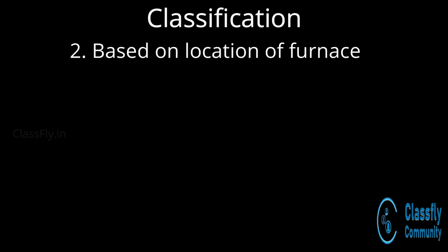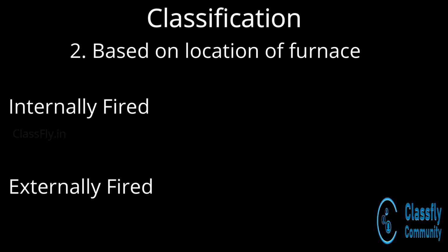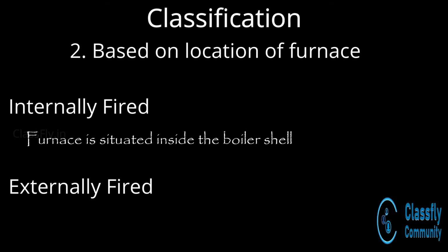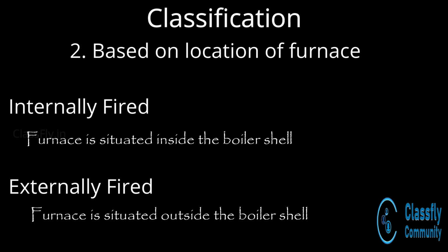The next basis of classification is according to the location of the furnace. Well, furnace is the chamber in which the fuel undergoes combustion. On this basis, it is classified into internally fired boilers and externally fired boilers. If the furnace is situated inside the shell of the boiler, then it is called an internally fired boiler, whereas in an externally fired boiler, the furnace is situated outside the boiler shell.